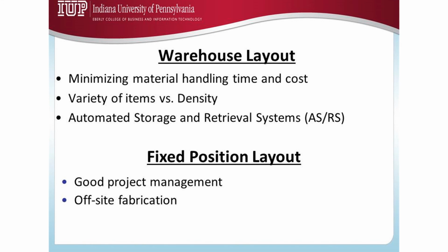The last one is a fixed position layout. Like I said earlier, a fixed position layout is not really a layout. It is more of people, workers, coming to a particular location and then building a ship, building a spacecraft, building a dam. These are fixed position layouts. What is important here is good project management, which is another topic we have discussed.